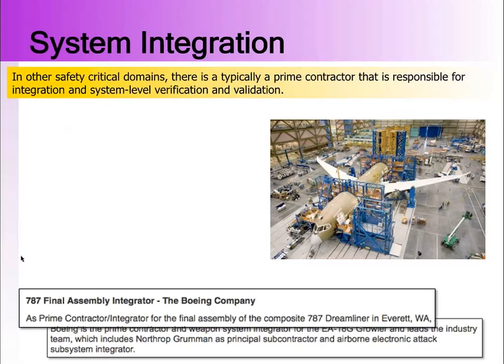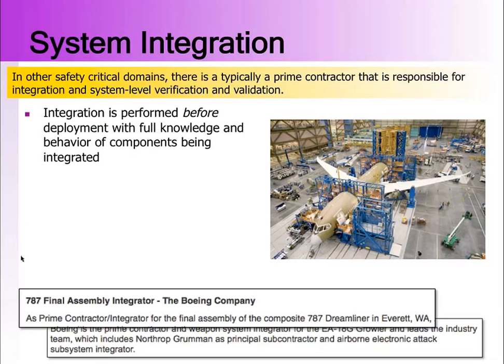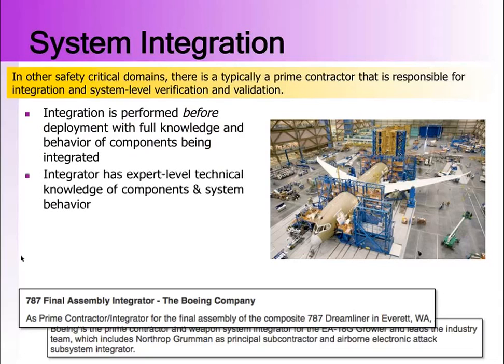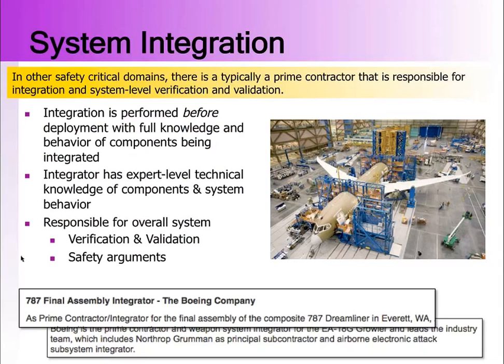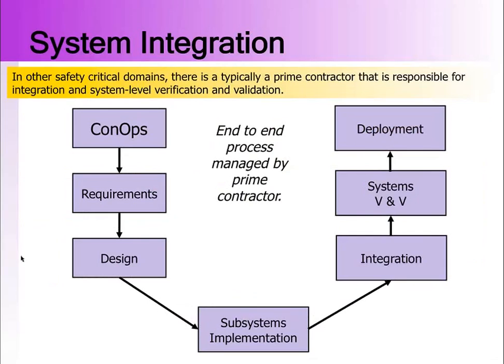And this is, again, I'm oversimplifying the case to some degree. But what you have in the avionics context and other safety critical systems is that integration is performed by a prime contractor that's responsible for the integration and system level V&V. So integration of components to get your system is performed before deployment with full knowledge and behavior of the components being integrated. The integrator has expert level technical knowledge of the components and system behavior, and is responsible for the overall system V&V safety arguments and certification.